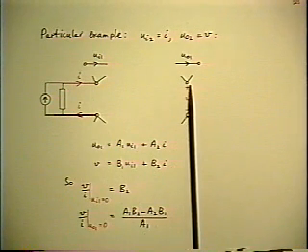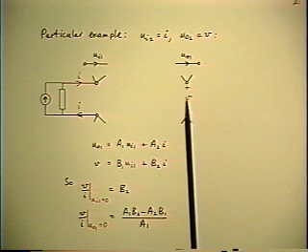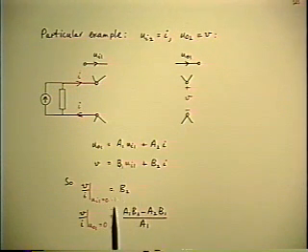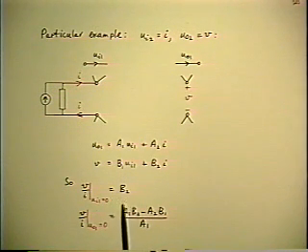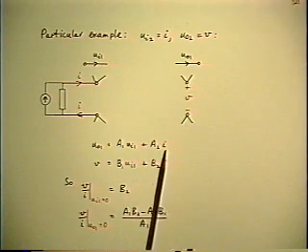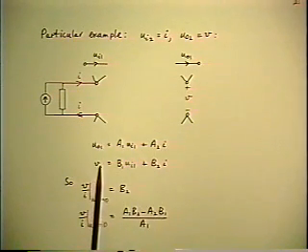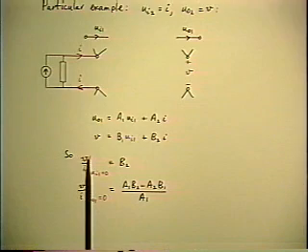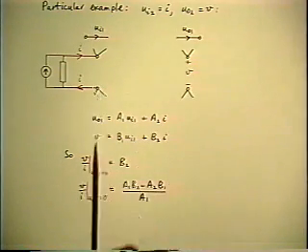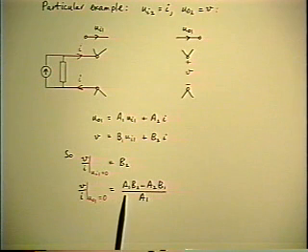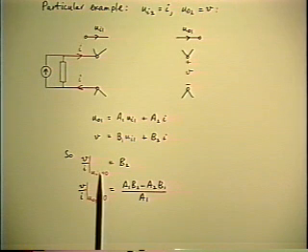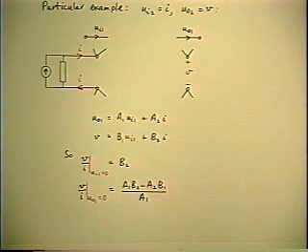Okay, that's identified input number 2 as a current. At the same time, I'm going to identify output number 2 as a voltage across another pair of terminals. So I can go through exactly the same algebra again, which is identical. The only difference is that UI2 now becomes I, and UO2 becomes V. So the two results that I already derived are now V over I, output 2 divided by input 2. And again, I get two different answers for the same quantity because they are calculated under two different conditions. So they're not exactly the same quantity.